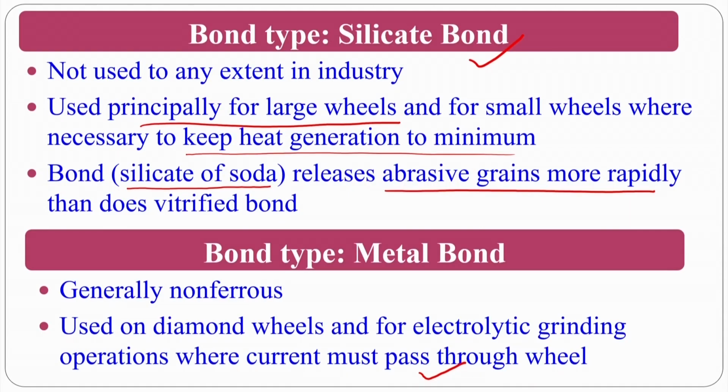This particular thing I am teaching you, electric discharge grinding and electric discharge diamond grinding, I will take up in an elaborate way in the upcoming classes. Just for your understanding, in EDM you know that both the workpiece as well as the tool should be conductive. So, here if I want to make the wheel conductive, then I have to go for metal bonding.